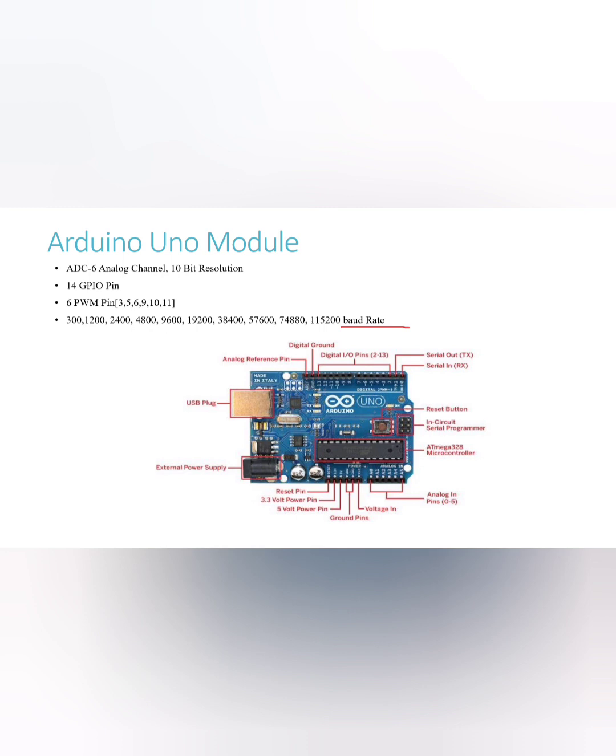The term baud originates from French engineer Emile Baudot. It refers to the number of signal or symbol changes that occur per second. Normally in Arduino we can take 9600, but we can change it according to the requirement. You can use USB with a computer to burn code. You can connect a Bluetooth module HC-05 to pins 0 and 1 for serial communication.